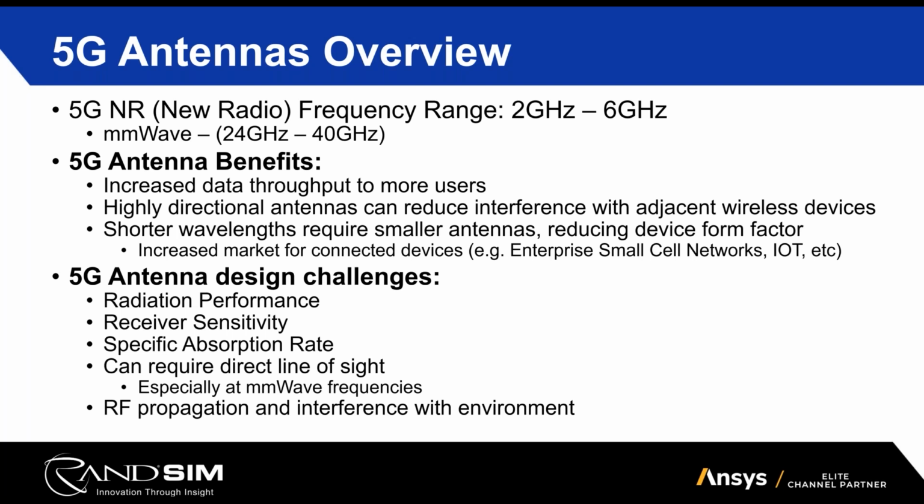Other things to consider: a lot of these devices are very close to the body. So making sure that you're not transmitting excessive energy into the body and causing excessive tissue heating, such as evaluating for specific absorption rate or SAR. That's always a consideration when we have wireless devices.